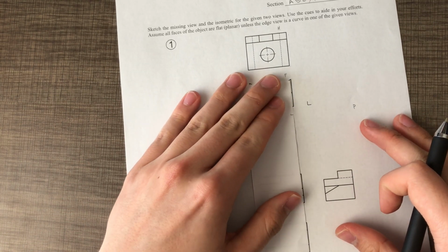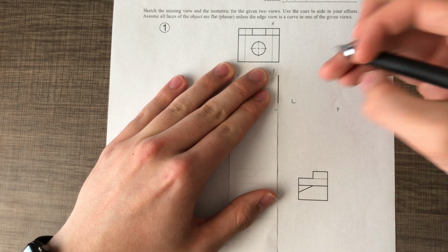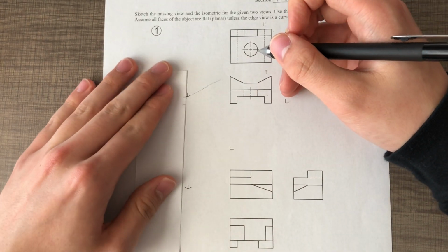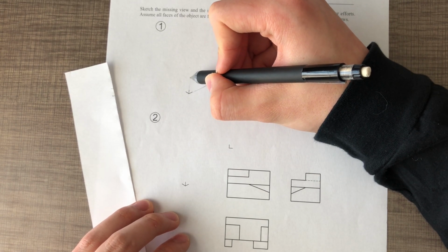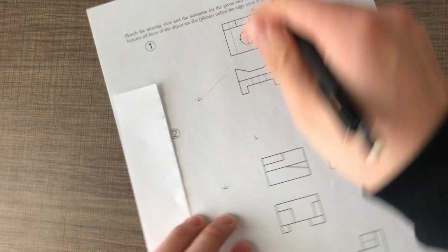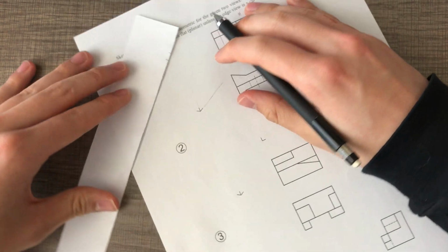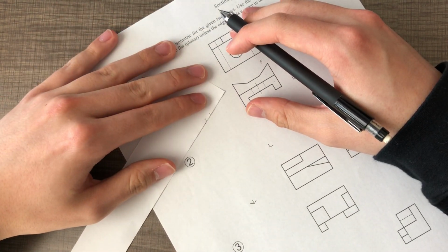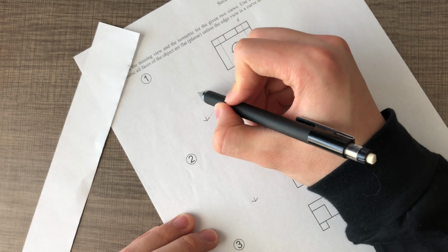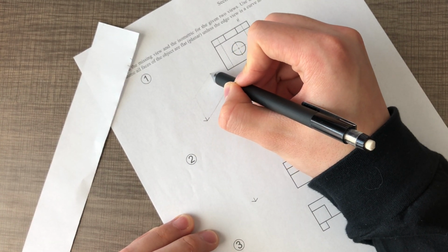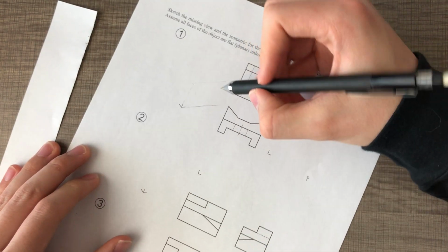Close enough. The height of my object is going to be this height, right? Height of the front view. So I'll trammel that distance upward. I can project the other two out parallel, so I can check my parallelism with this. Check it. And then bring this up.